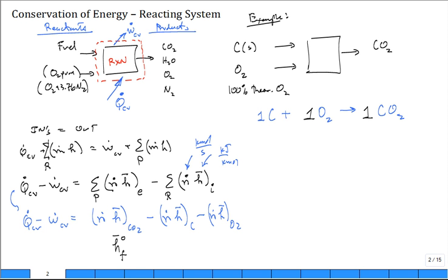So what does this measure? It measures the energy, or the enthalpy, associated with the chemical composition of that element compared to a reference state of base elements. So it considers how that element may have been formed, the enthalpy of formation, from more basic elements. So if I want to know H, it's the sum of the enthalpy of formation plus the enthalpy at the current condition.